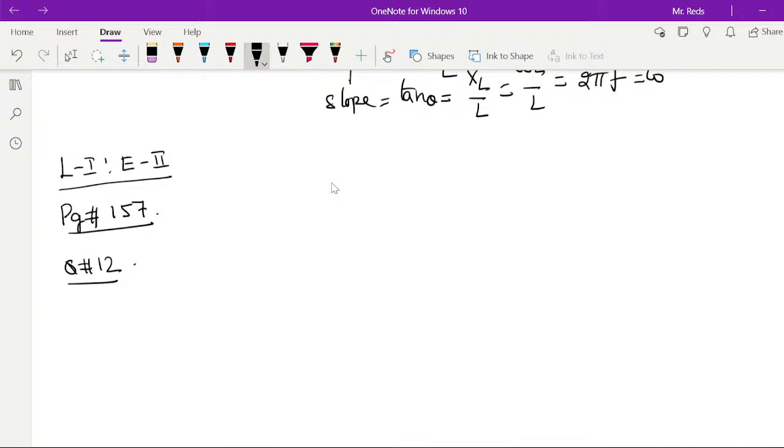So I already told you, if you want you can write it down, there is a note. When you are given the line voltage ratings, the line voltage is treated as RMS voltage. So here a 220 volt 50 hertz AC supply is given, which means in the supply voltage, V will be taken as VRMS.